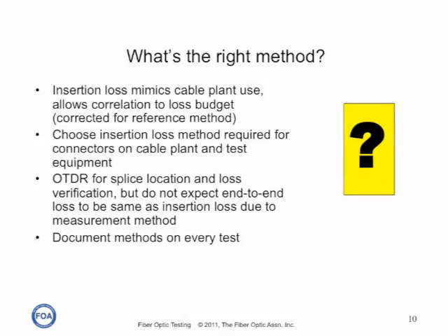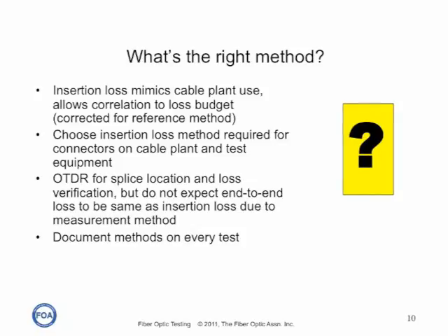But if you use a 2-cable reference, you'll measure 1 connector loss less than your loss budget, and with a 3-cable reference, you'll measure 2 connector losses less. You choose the insertion loss method that's basically required by the connectors that are on your cable plant and test equipment.